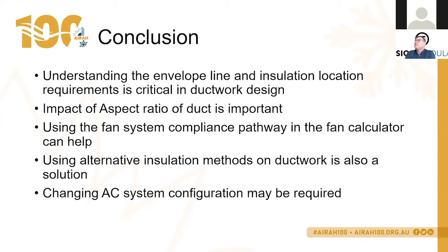There is a maximum amount of flexible ductwork in an index run of 6 metres. Well, it's per duct run. So it's not necessarily the index run, but it's per duct run. So any supply duct run to a supply point can only have 6 metres of flex duct. So each supply point can have 6 metres of flex duct to it.